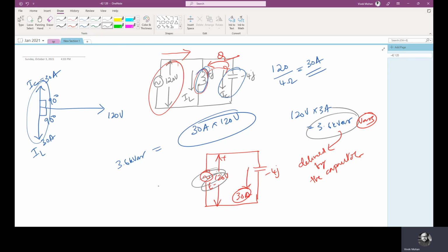It's just like a pendulum. It swings back and forth. So the capacitor acts as a temporary energy storing device which stores and releases energy repeatedly, accepting energy for brief periods and releasing it again. However, instead of storing magnetic energy as a reactor does, a capacitor stores electrostatic energy.